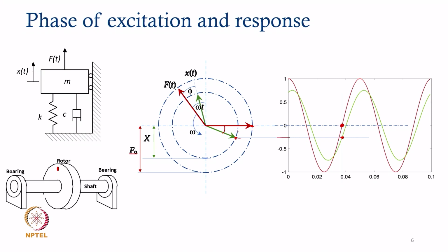So, after a certain interval of time, as this force continues to move up like this, the response vector will align with this and have 0 value later. This response, currently having a negative value, will have 0 value later at this particular instant of time, and this distance, which is in terms of time converted into angle, is going to be phi.